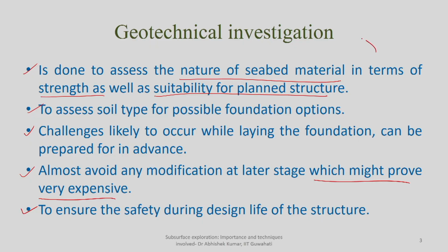You have to go for detailed investigation, but I am repeatedly telling you, it has to be done based on your preliminary investigation as well as geophysical investigation, which suggest that your selected site meets your requirements for the project. Otherwise, there is no point in going for detailed geotechnical investigation.